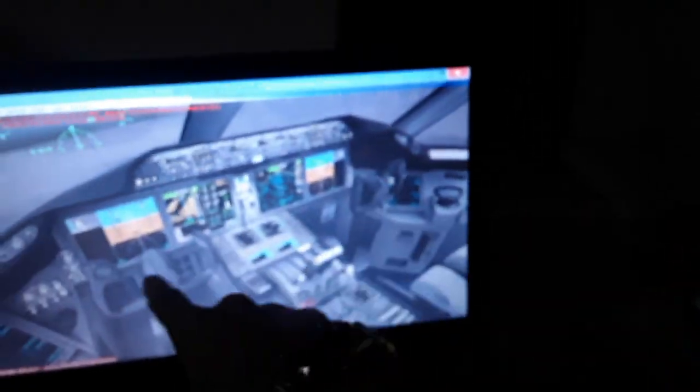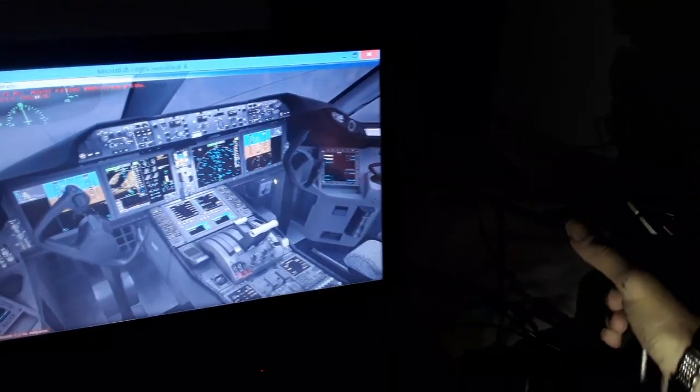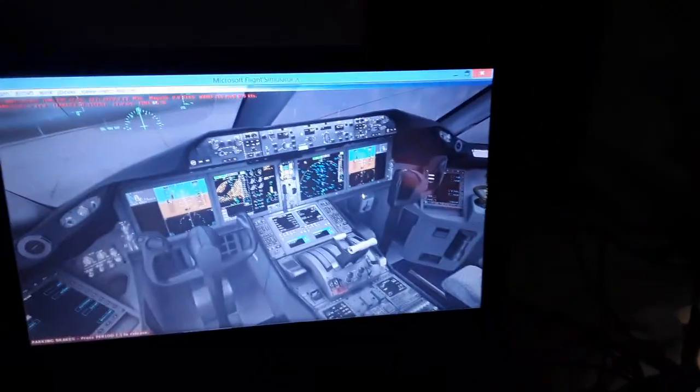So you will see over here. So I'll show you the flight control joystick deflection proportional to the yoke deflection. Both sides, the captain and the first officer, move together. They're interconnected in flight: all flight controls, rudder pedals, control wheel and control column. They don't move independently in flight like in the Airbus. You have the joystick priority and you can take control of either side, left and right. This is moving together unless you have a failure in flight.